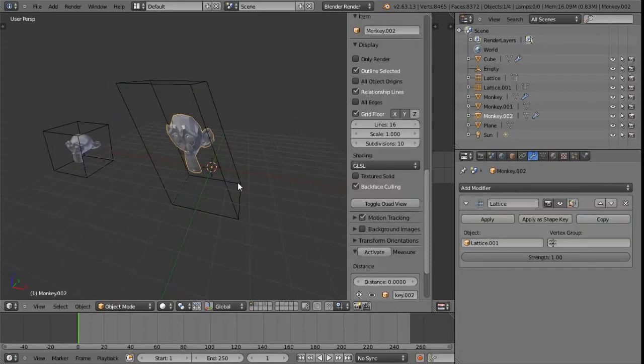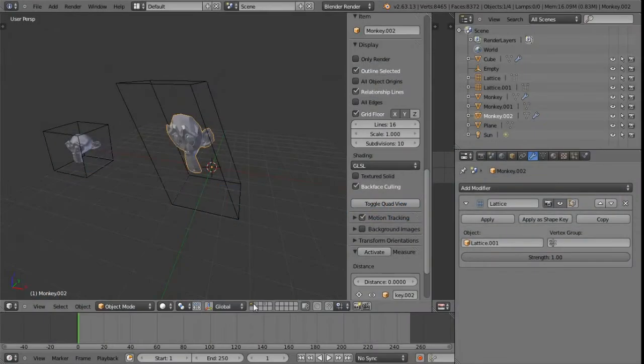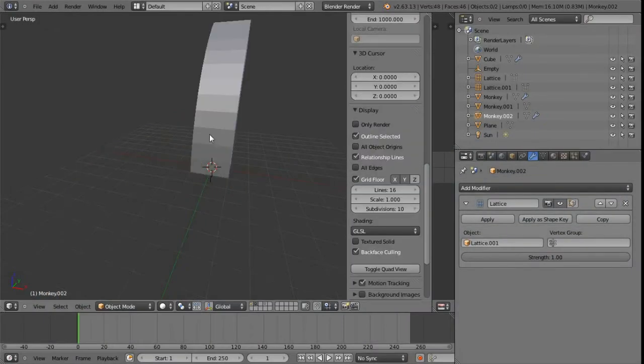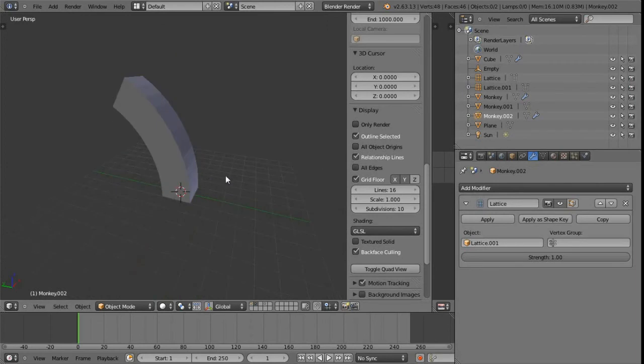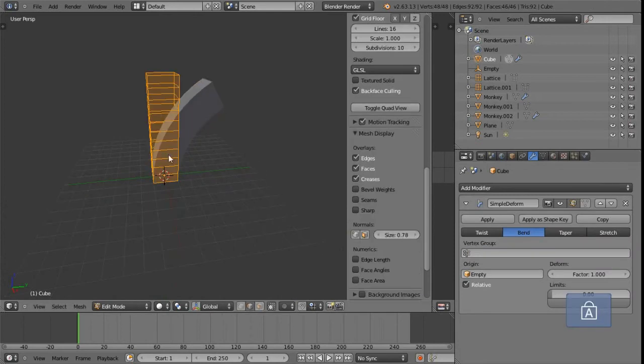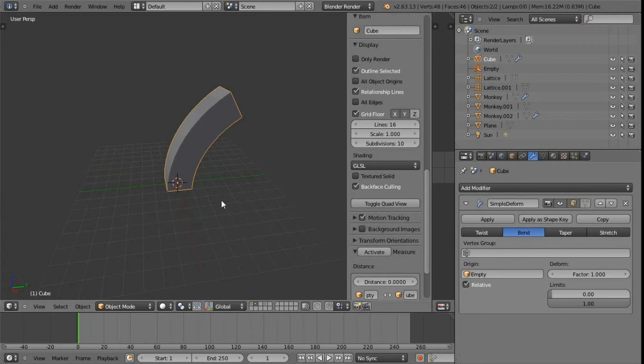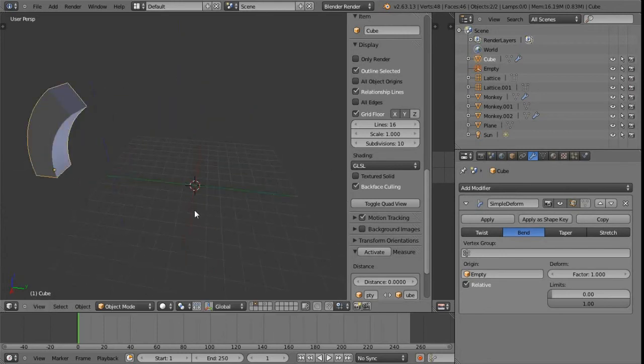So let's move on. I've got another couple of scenes down here in the layers. I'm actually just going to click on the second one just to see this. Here's another deformer. This is the bend deformer at the moment. Just got a simple subdivided, extended and stretched cube, which is now being bent over. This is a typical thing that you might like to do with, well, this is basically what I tend to do with the bend modifiers within Maya. So it's that kind of behavior.